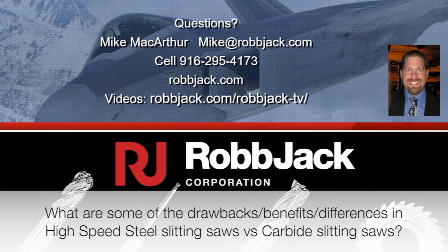In general, and every application may be different, a high-speed steel saw may be better suited than the carbide, but usually carbide is a little better suited. High-speed steel is a little tougher than the carbide in its ability to resist chipping.